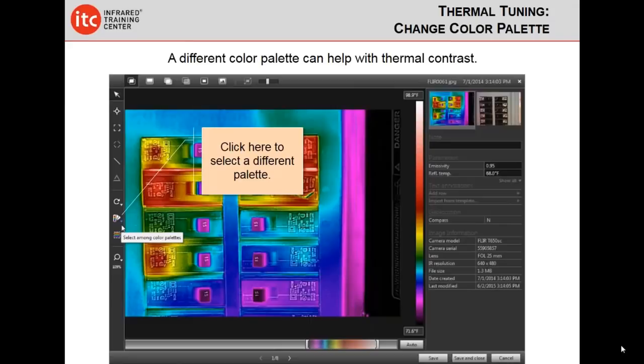Hey, Mike, I really appreciate your question. When we purchase a sUAS camera, of course, we don't want it for one application. We're making a huge investment here. You mentioned roofing and electrical, so here's my opinion. I'm a real fan of the Zenmuse XT radiometric version, and the reason for this is the resolution. The resolution is huge, and this is a very stable camera on the gimbal. The other lens I would recommend would be the 13 millimeter for that application. It's not real wide angle. We have 19, 13, and 9, and the 13 is in the middle. I would recommend the 13 because you're getting a mid-range lens application. And then the Inspire 1 works great for that. In my opinion, that's what I've flown in those three applications, and it works great. Hopefully that helps answer your question.